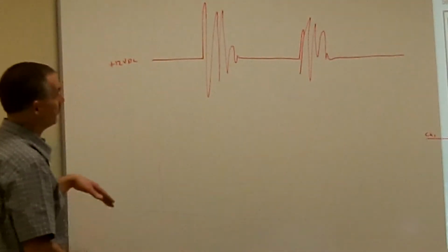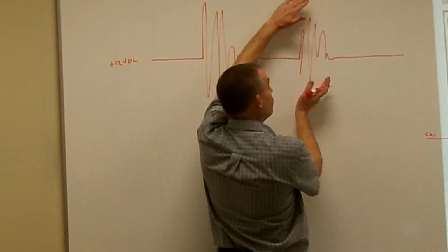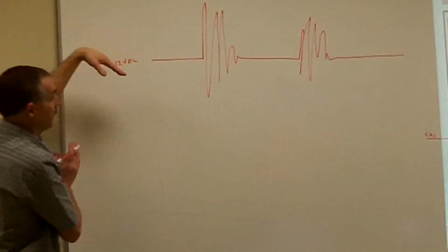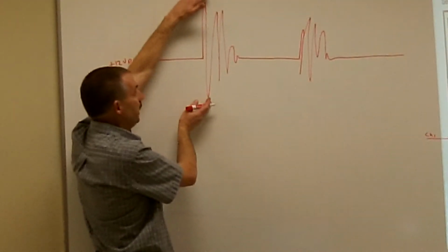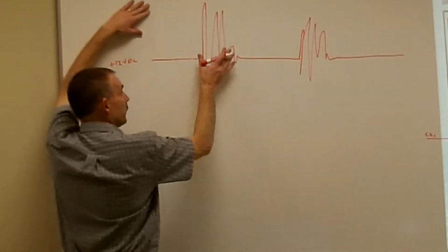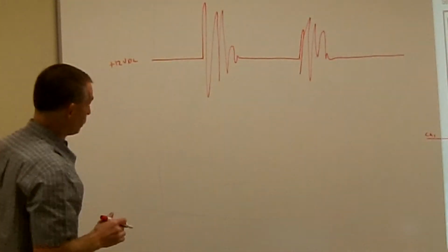It's alive. So I'm getting what we call common mode. It's noise. I know it's coming from my servo drive, but now I'm trying to figure out how to eliminate it. These voltage spikes are almost 50 volts peak to peak, so it's heating up our device under test way more than I want. I want just a nice constant 12 volts.